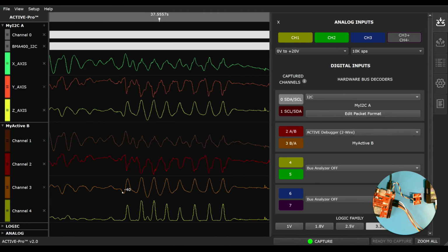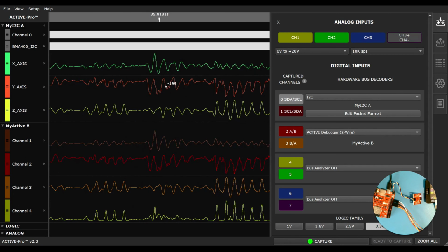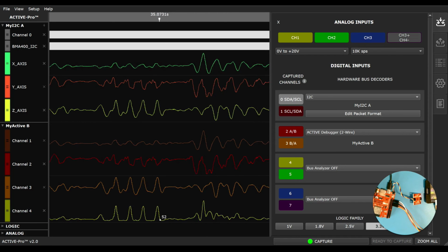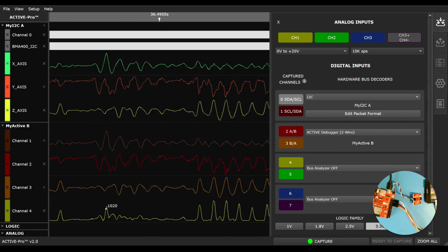So you then see after the stop occurs, the I2C bus is reanalyzed and redisplayed just like we did before. And guess what? See any similarities? It's exactly the same. So we gathered the actual data off the I2C bus. We actually gathered the exact data that the microprocessor received. And then guess what? We received a curve, which is the magnitude that you cannot get off of the wires. You can only get this information in the microprocessor after it has computed the algorithm.